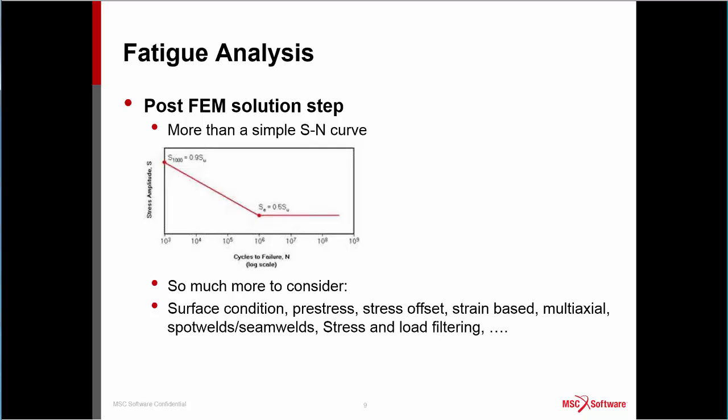So everyone has done at least one fatigue calculation somewhere in your career. If you're a student, you do a simple SN curve lookup. You might use one of the equations, Gerber or Soderberg. You'll do this in a couple of homework problems, maybe a test problem. You might even have a homework problem that considers the surface conditions or pre-stress.